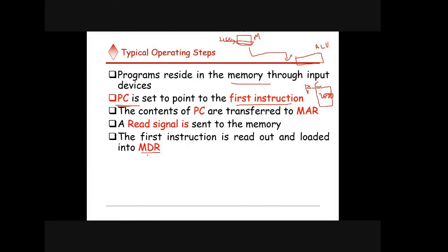I told you now that instruction I should execute. So before executing that instruction, I should also make sure that IR is the instruction register. The currently executing instruction should be there in your IR register. So what should be the next thing? Now the instruction fetched from the memory unit is present in the MDR.